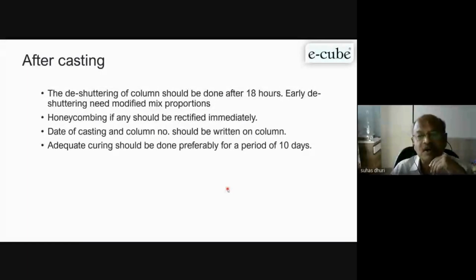But if the concrete was done late at night, maybe 12 o'clock, when they finish some columns, in the morning he will start deshuttering and will find there is a deflection. So that precaution has to be taken. Instruction has to go to the site properly on when to deshutter the columns or verticals at least. For slabs we know it is required after a few days.